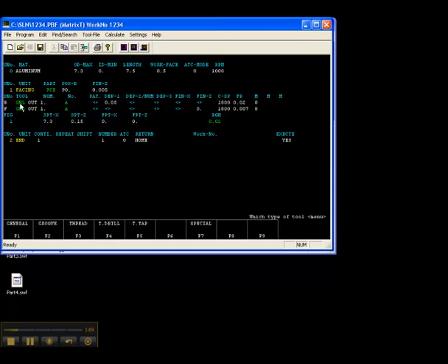Remember we had a tool info page where we filled out the data about the roughing tool. This is the tool ID, and this is the depth per peck from the cut info window. Over on the right side here we've got the spindle speed, that's from the tool info window. And the roughing feed rate, that's again from the cut info window. Because in the cut info we told it to do a quote-unquote cleanup pass, it developed a finishing tool as well. The finisher is just a copy of the rougher. So if you wanted a different tool, you'd have to edit it right here in our editor.